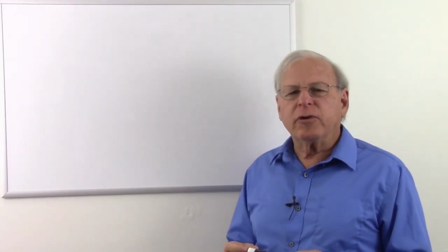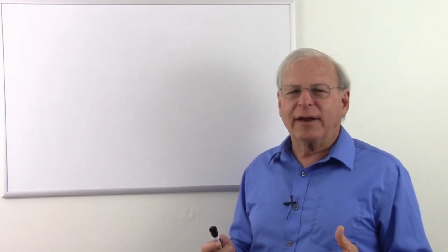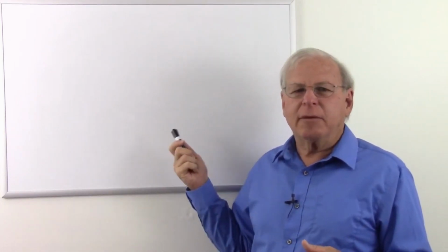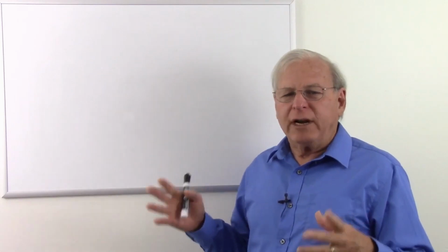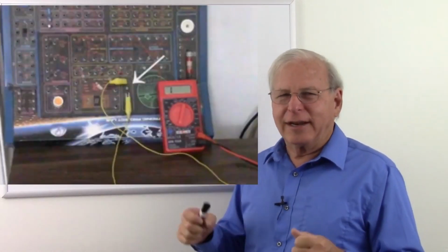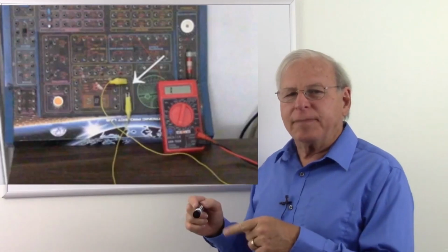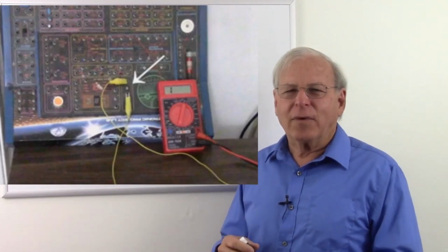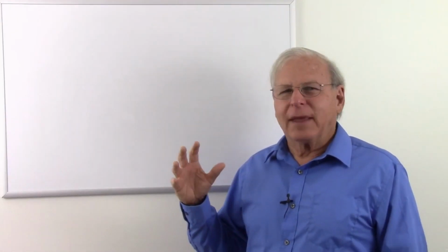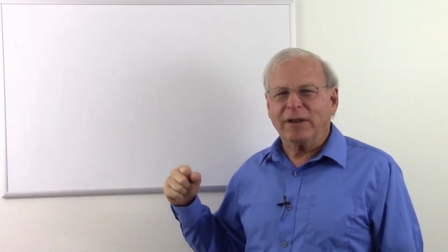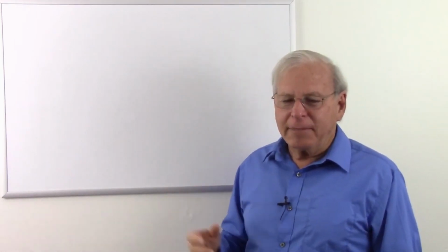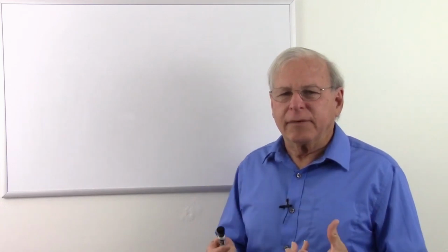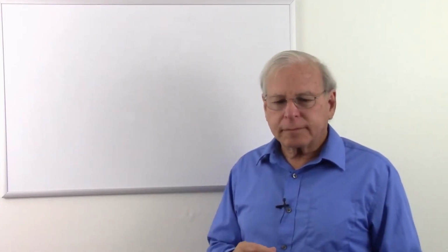I made a video doing a review on some flashlights I bought at Amazon that did not live up to their power output as far as I can tell. And I simply used a cadmium sulfide photocell that was on this old Radio Shack 130-in-1 little project kit, and I used that to compare the light output of these flashlights to some other ones. And I don't know if the other ones were accurate at all, but they did not live up to the 1500 lumens that were advertised. I'm pretty sure about that. But anyway, with a photoresistor, as the light on it increases, the resistance goes down.